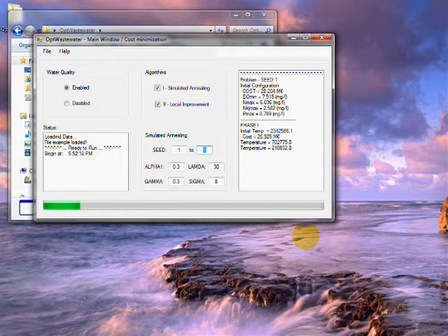The simulated annealing algorithms have been applied with remarkable results to several hydraulic system planning models. The algorithm starts with any initial feasible solution, the incumbent solution. Then, a candidate solution is selected at random in the neighborhood of the incumbent solution. Candidate solutions better than the incumbent solution are always accepted, becoming the new incumbent solution. Candidate solutions that are worse than the incumbent solution may or may not be accepted. This is important because it helps the algorithm to avoid getting stuck in local optima.